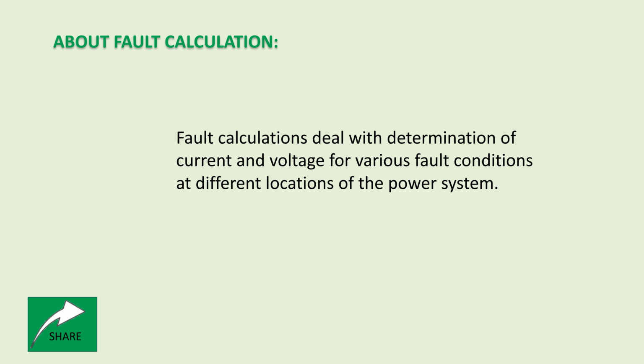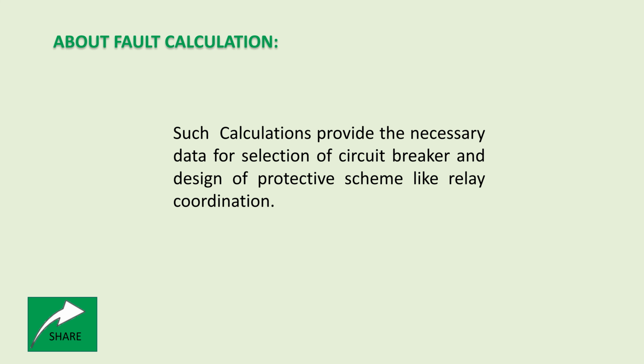Fault calculations deal with determination of current and voltage for various fault conditions at different locations of the power system. Such calculations provide the necessary data for selection of circuit breaker and design of protective relay, like relay coordination.